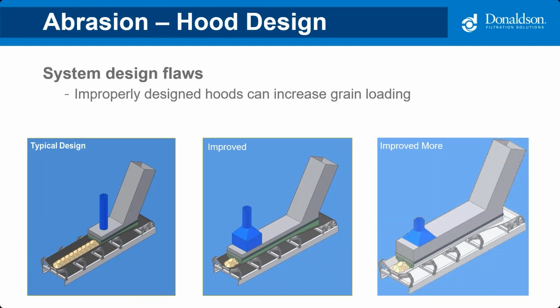Maybe you want to elongate that capture area a little bit to help the dust settle down onto the conveying belt. But more importantly, you're going to want to get that straight pipe out of there. And you're going to want to allow a little bit of a drop zone where all the heavy sand is actually going to stay on the conveying belt where it's supposed to be, and it's not going to get sucked in. And so just a real simple change in your pickup points can make a lot of difference in the dust collector.